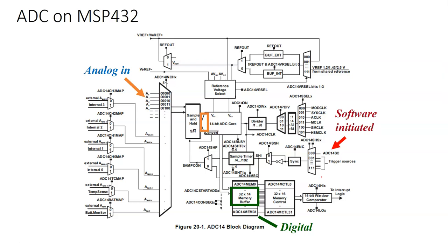So just like we saw with the timer hardware and software, we're going to set up the ADC and configure all these parameters: the internal ADC clock frequency, the sampling frequency, the reference voltages, the input, the clocks. And then finally, the last thing we'll do is in software set a bit that actually initiates the ADC to start sampling. We'll then have an interrupt generated when a sample is taken, and inside that interrupt we can read that data and do whatever processing we need on it. Finally, I've also posted some sample code on Canvas that you can use for getting started on the ADC assignment.